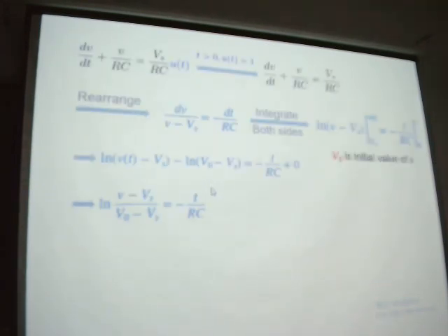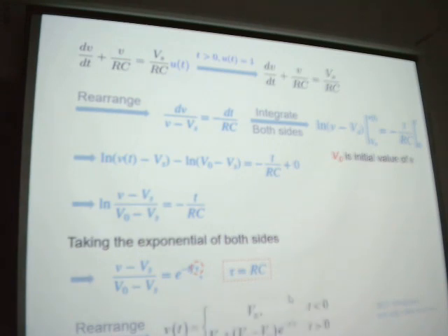So here we can easily get that if t is smaller than 0, the circuit is not closed, so the value of V is the open circuit value, Vs. And if t is greater than 0 and we rearrange this function, we get this one. This is an important function for us.